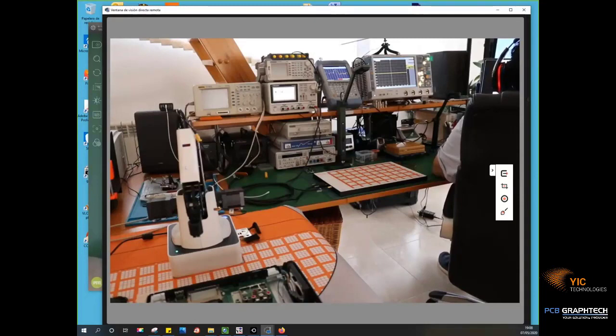These problems have three important parameters to control. One parameter is the distance. When you have a short distance between the culprit and the victim, you have more probability of having problems. Another important parameter is the frequency. Typically, we will find more problems if we work at higher frequencies. Obviously, you can find problems at 50 or 60 hertz, especially magnetic field problems many times.